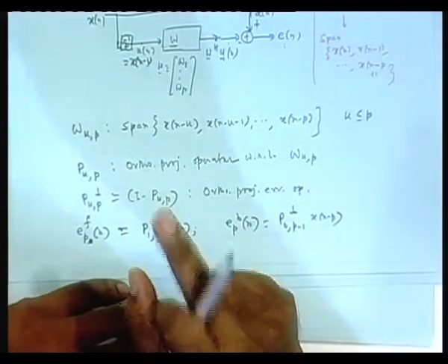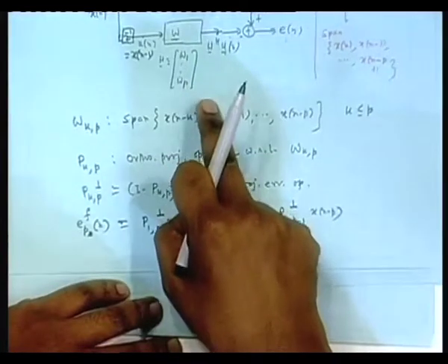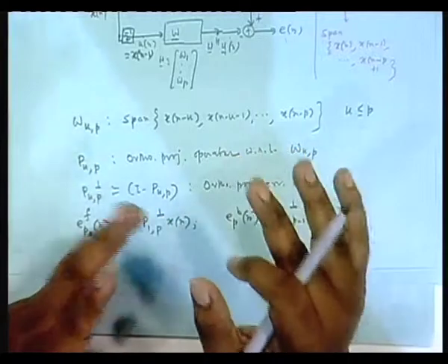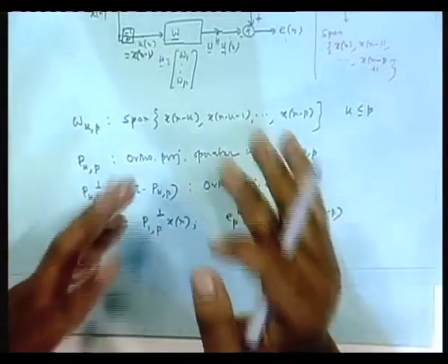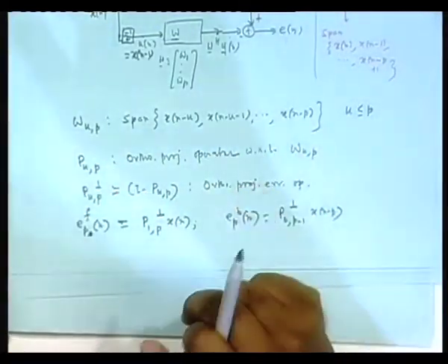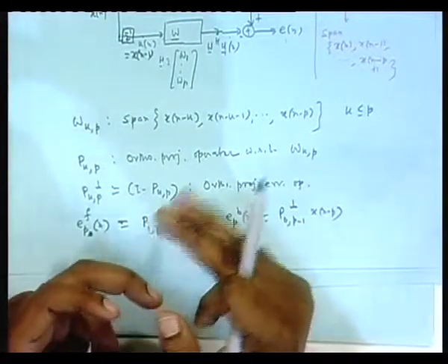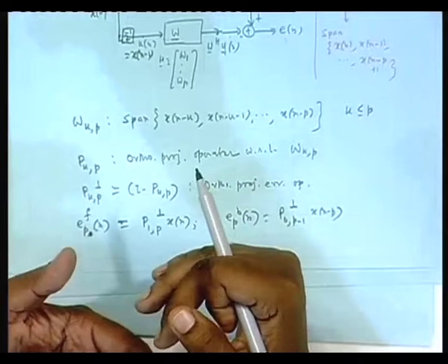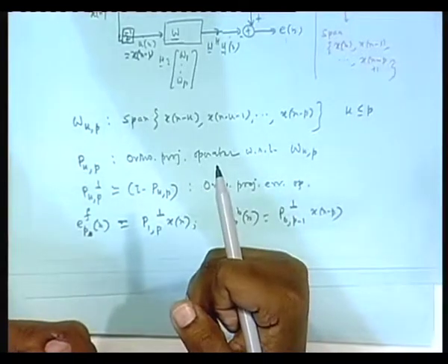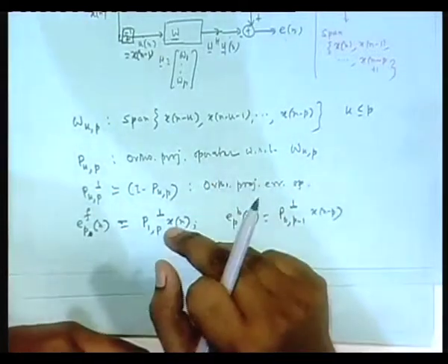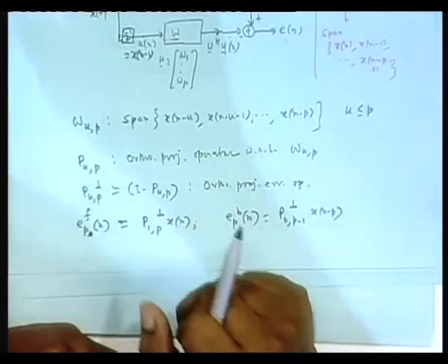Linear combiner coefficients are independent of n, which we have seen in a general case. Now, this error I want to take its mod square, or the error multiplied by its conjugate, and take the expectation. That is the norm square definition in terms of our Hilbert space. Multiply a random variable with its conjugate, this mod square, take expected value.